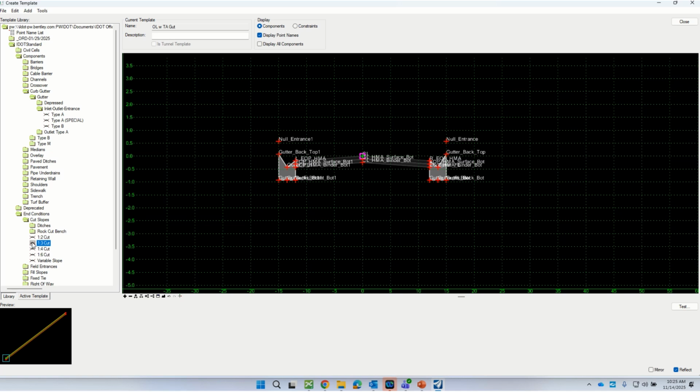But that does not mean that we necessarily need to create a new template. We're just going to use something that's applied to the corridor. Some of these tools are called, and we'll get into more detail on that later, point controls, parametric constraints. We're going to use display rules. There's a whole number of tools that we can use. In condition exception. There's not that many, but there is a handful of various tools that we can use later to modify just the basic template.